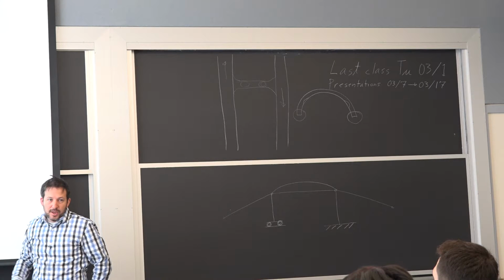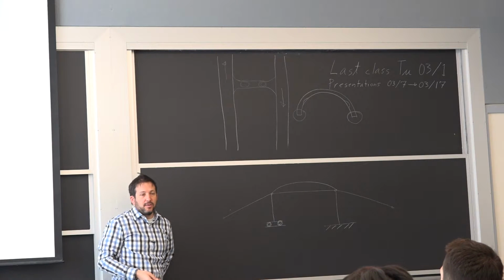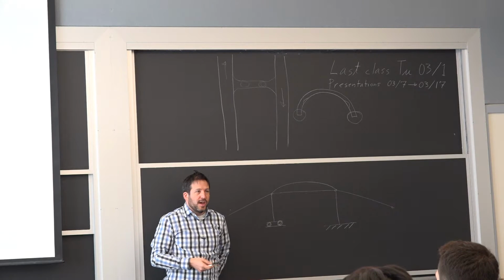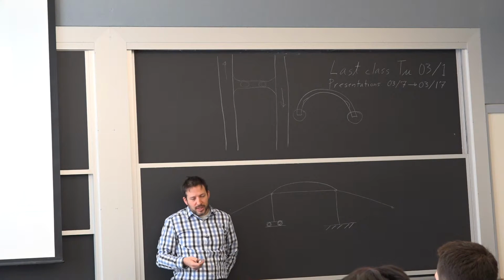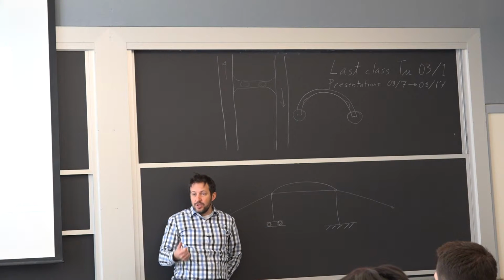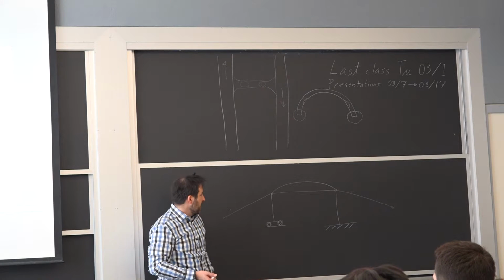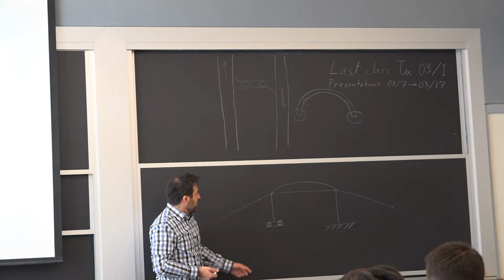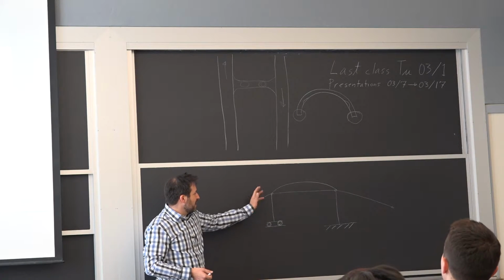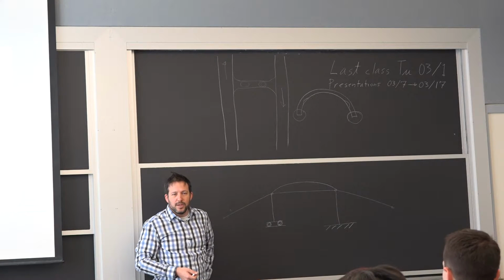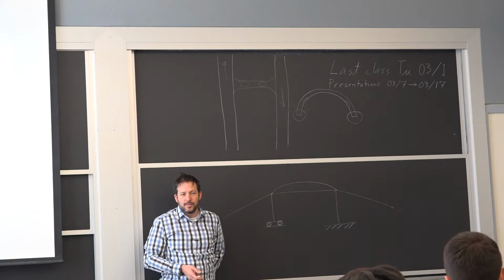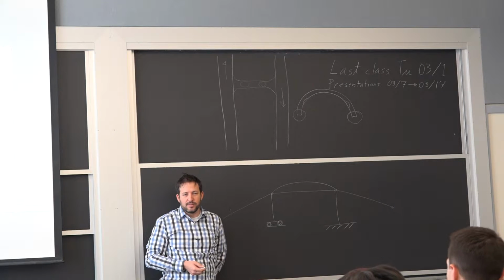Over time, your factor of safety is going down. Is it because you have more events going on? That's one option. Your conditions are changing. So back in the 50s or 60s, they didn't necessarily have the kind of salts that we use nowadays to make sure there's no ice on the bridge.